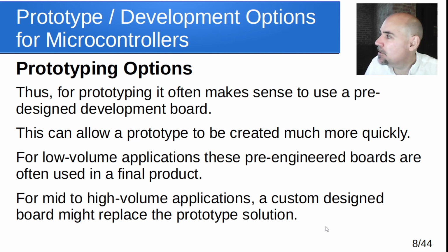Now, if you are interested in designing something from scratch, you can still do that. It just takes a little more effort because you're going to have to learn what support circuitry the particular microcontroller you want to use needs. Like, what does it need for a clock? What does it need for a power supply? Does it need a special reset circuit? Does it need special capacitors for noise filtering? You'll have to learn all of that stuff, and then build that into your design, and that takes time. So if you use a board that's already designed to do that, you can get to a prototype more quickly because they've already done a little bit of the engineering for you.